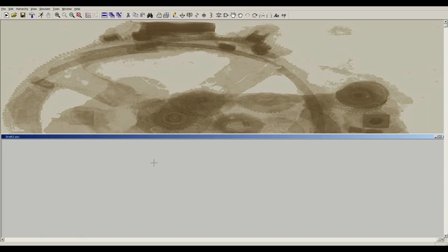The first thing to do is lay down all your components. Hit F2 and type voltage into the search bar. Double-click to lay down the component. Right-click where it says V1 and you can rename it to whatever you want. I like to call it VS for source voltage. Right-click on the symbol to enter the parameters and copy the magnitude from the Python script. Your frequency will be 60 Hz in the United States, and for this simulation, I find it works best to have 3 wave cycles.